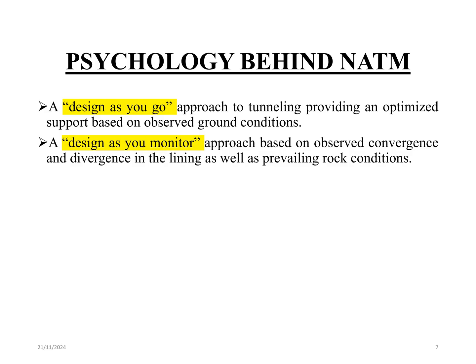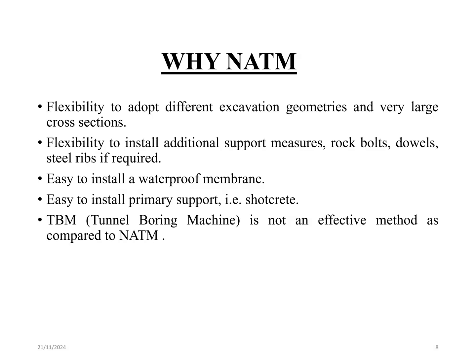Let's discuss the philosophy behind NATM. It emphasizes a design-as-you-go and design-as-you-monitor approach, optimizing support based on observed ground conditions and convergence or divergence in the lining. Why should NATM be used? This is because it offers flexibility in excavation geometries and large cross sections, easy installation of additional support measures, cost effectiveness compared to tunnel boring machines, and easy installation of waterproof membranes and primary support.